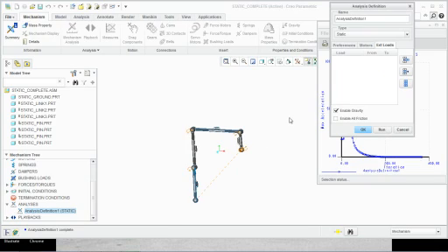Okay. So that static analysis tells you static equilibrium positions. It's very important that we take care of this issue, because if the part's not in static equilibrium, and let's say, I'm just giving a hypothetical situation, if you transport this part or this big assembly or a machine, it's not in static equilibrium because of the vibrations on the road or the vibrations induced by the truck that's carrying it, that could result in resonance also.